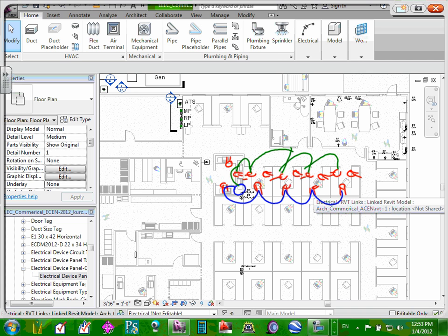This is already manufactured. It's pre-wired, guys. That's how we wire. And then for the last one here, I'm going to use black. You grab all these receptacles, and the leftover ones here and here, and you bring it from here. Here's what your circuit looks like. Does that make sense? This is a 3-phase circuit. A 20 amp circuit feeds one set of receptacles, another 20 amp feeds another set, and another 20 amp circuit feeds a third set of receptacles.